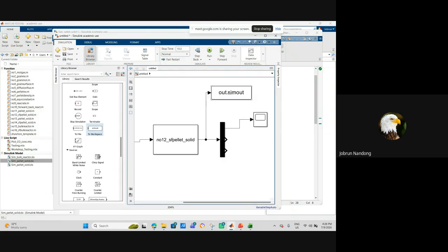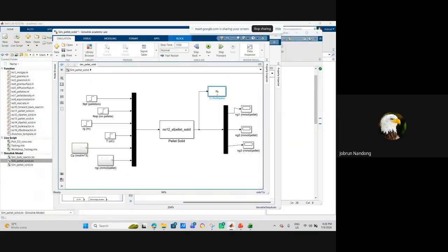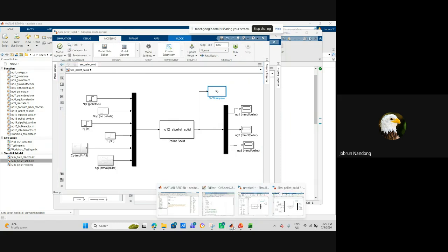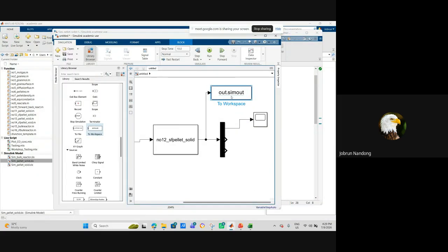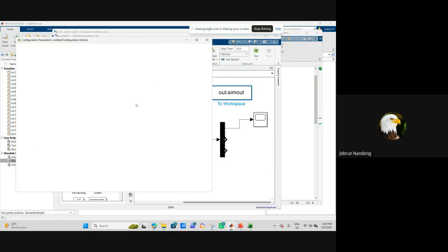Now here, normally they indicate the name of a briefcase. The briefcase contains many variables there, and you just call it out. If you want to change this so that you make it explicit like this one, which is an explicit name XG, what you need to do is go to the modeling part here. There's a model setting. So let us try that one. Now I want to make it explicit. So you go to modeling, model setting, double click, just click on this.